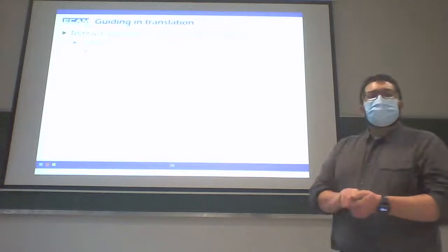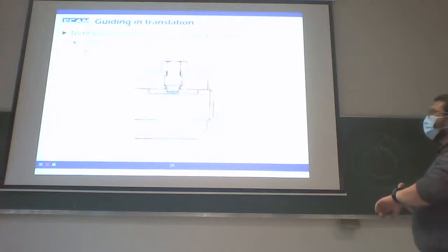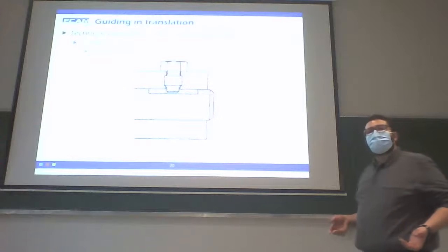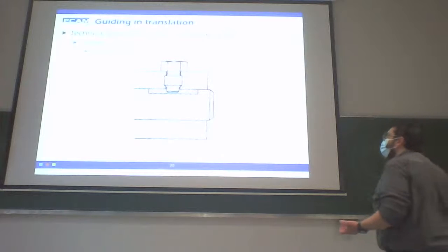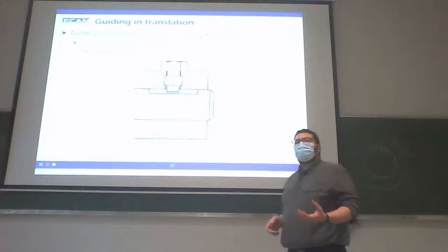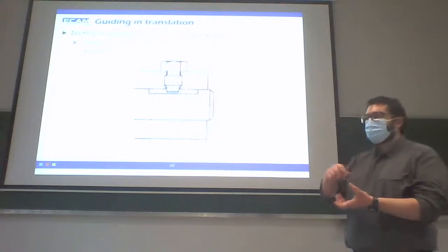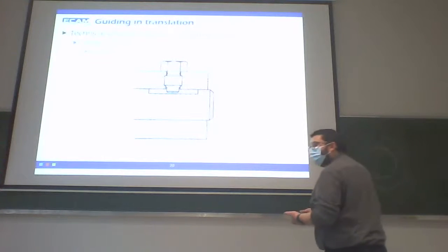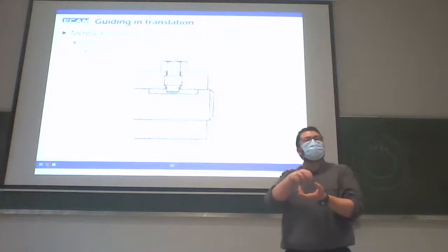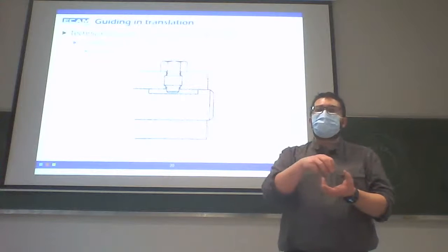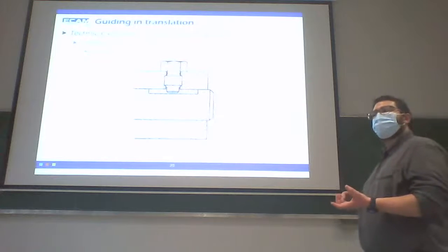We can also use a screw inside the slot to stop the rotation. So inside of the shaft we'll have a groove, almost like a key seat. Inside the ball we have a threaded hole. Inside this threaded hole we'll screw a small screw with a specific point. And this point will be inside of the groove of the shaft to stop the rotation of the shaft.